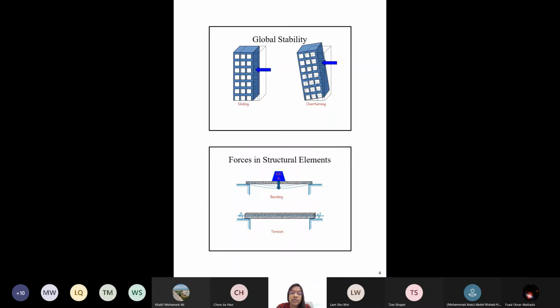On the other hand, when you twist the circular section, it's peculiar to the circular section only. That is, the application is only axial. This is axial. Other cases we are not discussing now. Only axially applied couples. When you twist the circular one and cut at all the places, it will be the same because there is no edge, it is a smooth surface. All become rhombus of the same size, or equivalently, all are rhombus of more or less similar shape and size. So warping is not occurring in a circular section.